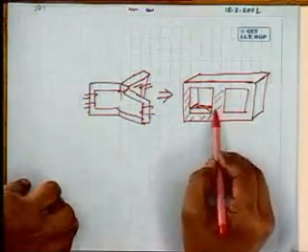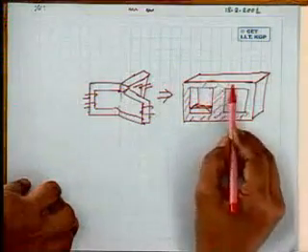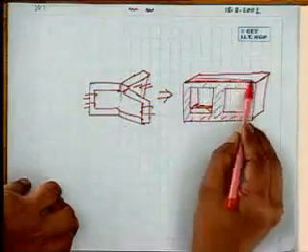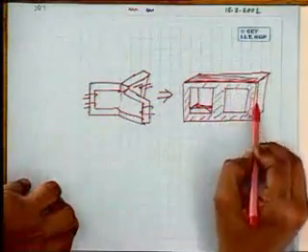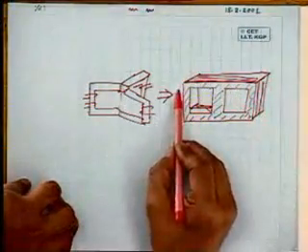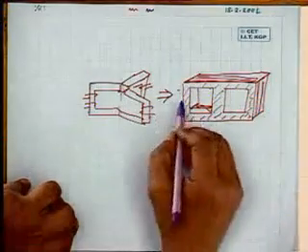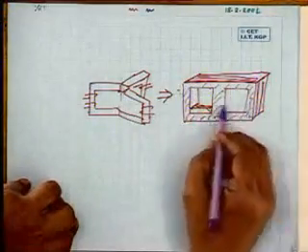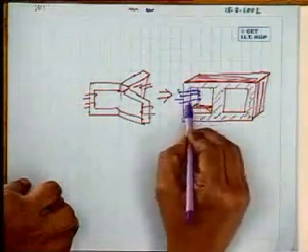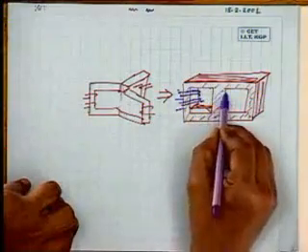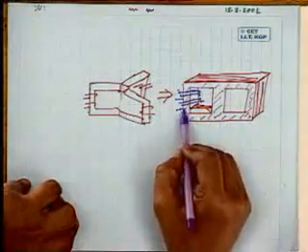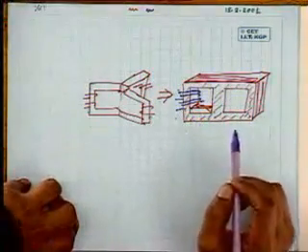These portions are iron. And stampings are stacked together to give you the thickness or width of this one. And windings you place here. On this, there will be 3 limbs now. On each of the limbs you place 2 sets of winding. One for primary, another for secondaries. Here also I am not drawing, for clarity. So each limb will correspond to a particular phase.